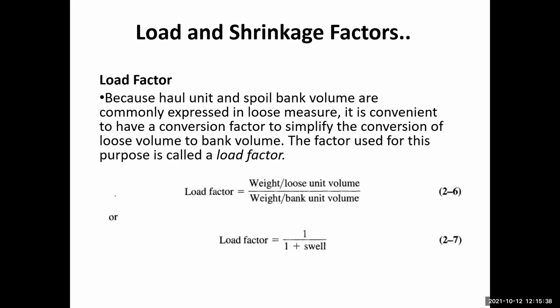Okay, so this is just the ratio. I mean, this is just the same formula as before, but we have said that the weight per loose unit volume divided by the weight per bank unit volume, in this case we can call it the load factor. So for example, if in the previous formula, what was the formula for the swell?